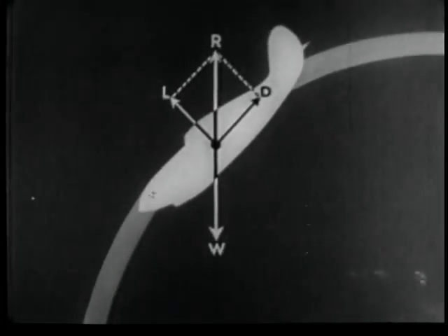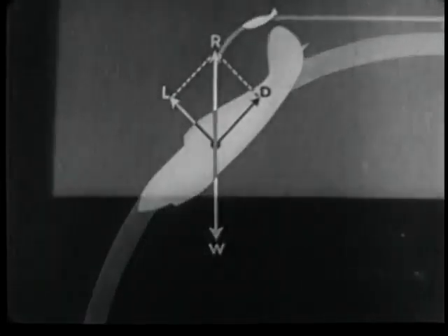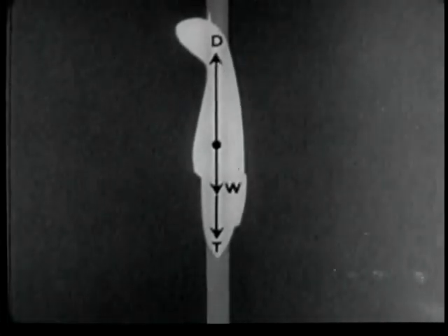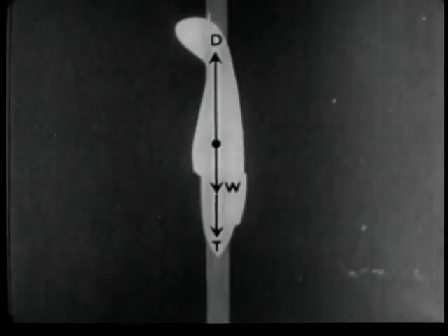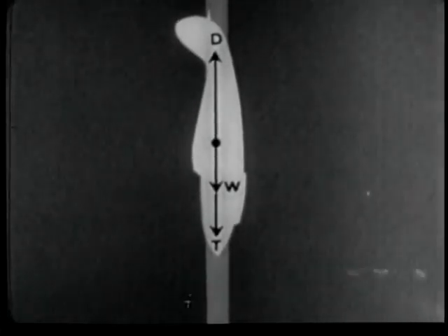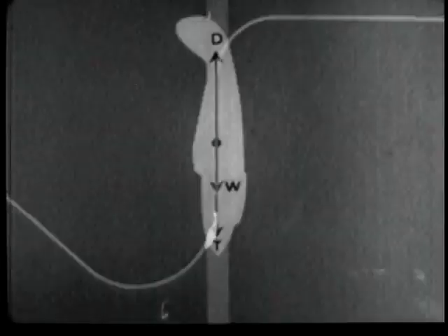Lift decreases, since in this attitude the weight of the airplane is opposed by the resultant of lift and drag. As the flight approaches the vertical, speed increases until the terminal velocity is reached in the so-called vertical dive. In this condition, lift is 0, and the weight of the airplane plus its thrust is opposed by drag alone.